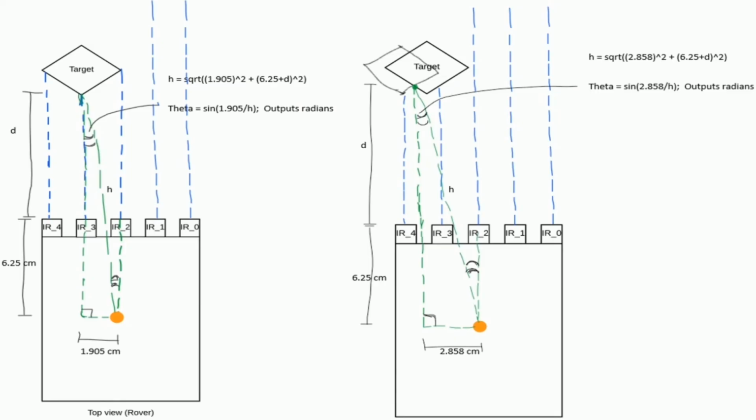Ideally, the targets would always be perfectly aligned like the drawing on the left. Here I can easily calculate theta and the distance to the target using trigonometry. A more involved solution, like the drawing on the right, consists of taking both extremes of where a target or obstacle could potentially be and then estimating to the middle of that object. This is because there is a slight gap between the sensors where the object could float from one extreme to the other. From there I would calculate the degrees to turn and the distance to the object, same as before.